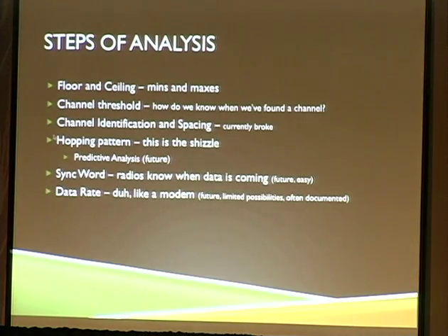And then we will do analysis on the packets and identify the sync word, the 2 bytes that tell the radio to start listening, is this for what we're after. So once we do that, we can set that in the radio code and not worry about it anymore. And the radio registers handle all of that nonsense. So it goes 10 10 10 10 10 10 10 10 sync word, and then we know we're sniffing.